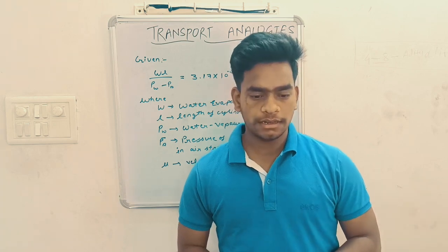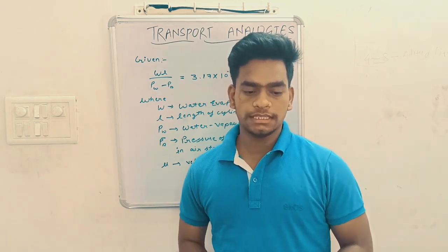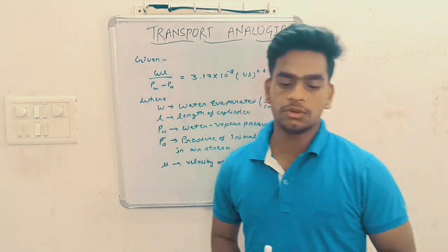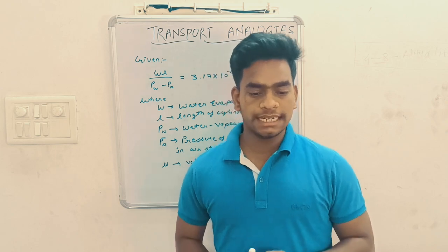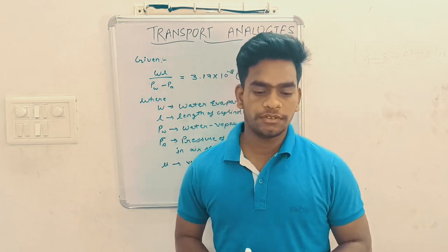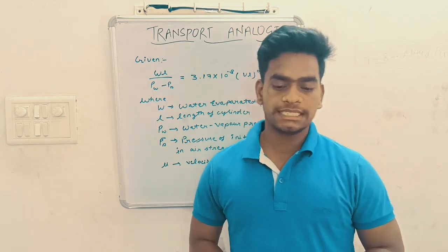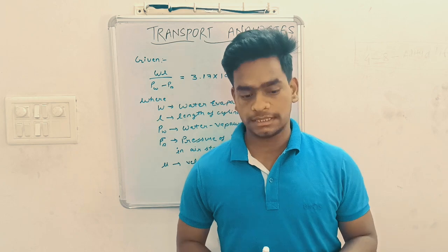Now, in the B part, we apply the relationship to a real situation. We have a naphthalene cylinder exposed to flowing stream of pure CO2 gas at 100 degrees Celsius and 1 atm pressure. The cylinder has a diameter of 0.075 meters and length L is equal to 0.6 meters, and the CO2 is flowing at 6 meter per second.